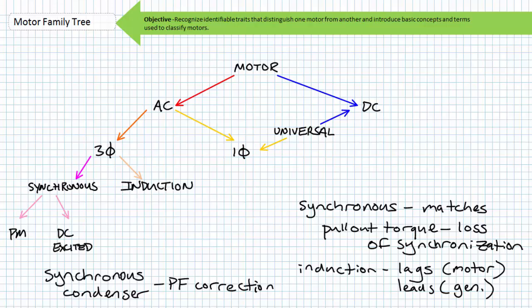This role is that of a synchronous condenser. A synchronous condenser is a very neat device that performs power factor correction for another electrical load by varying whether it supplies or consumes reactive power, i.e. acts as a capacitor or an inductor. Ideally, the resultant power factor is corrected back to unity.